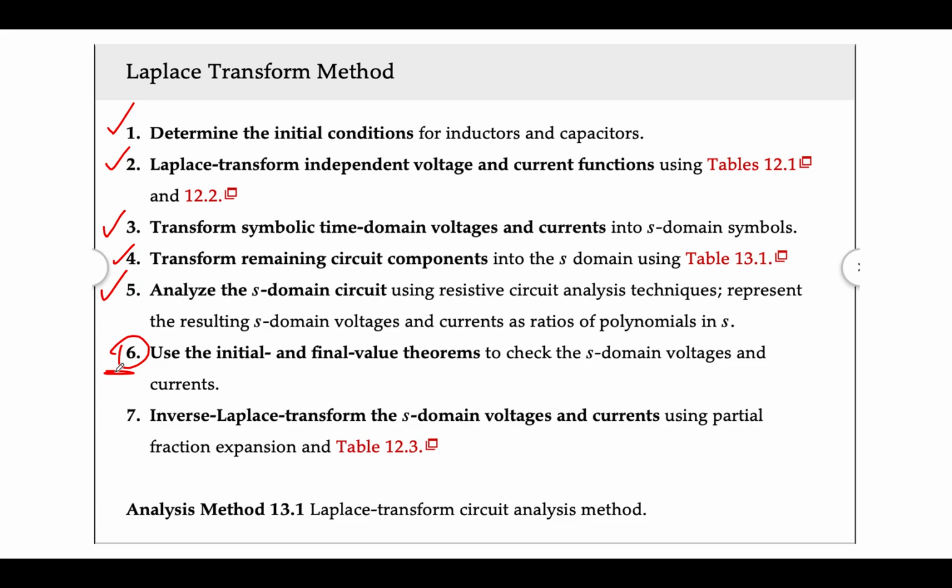There's nothing weird. Obviously, if you're analyzing a real circuit, you also want to make sure that you don't have any undefined functions or singularities or things that are going to transform back into impulse functions or their derivatives, because it's unlikely that you would get something like that in a circuit. You're typically not going to get hyperbolic sine and cosine unless you've got a source that contains that. So typically, when you get a function in the S domain, it'll be a polynomial. The denominator of the polynomial will be of higher order than the numerator, and the solutions will either be exponential decay, a polynomial in time like a ramp, or sinusoidal or step functions.